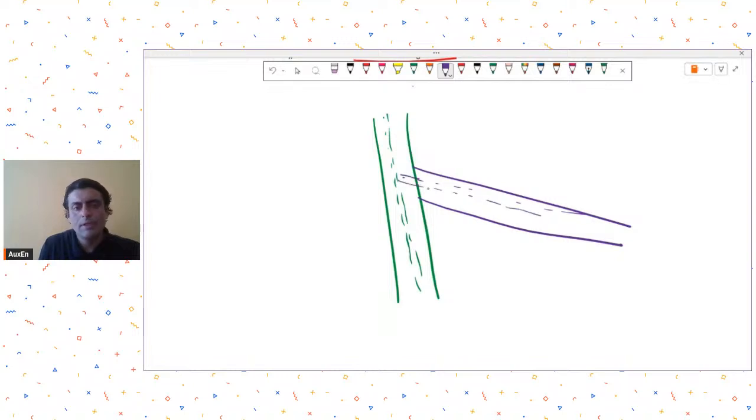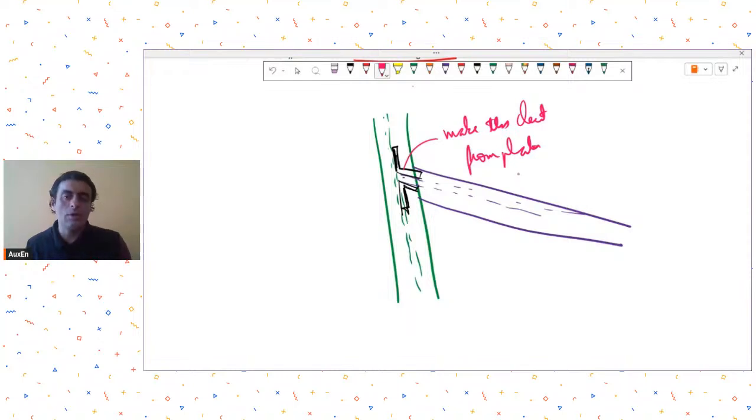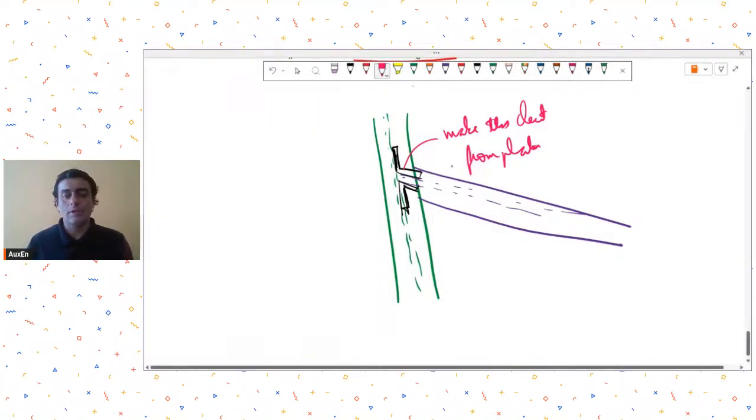The problem here is that providing angular cleats like this can be challenging. Although some people do provide these kinds of cleats also, where they make the cleat from individual plates, instead of going for hot rolled cleats or standard angle cleats. That is one way of doing it.